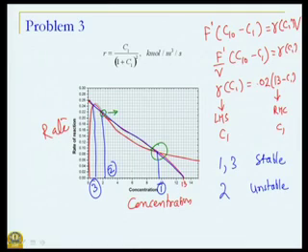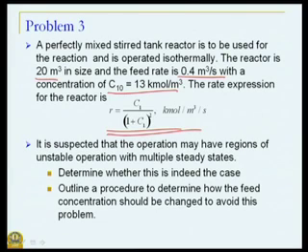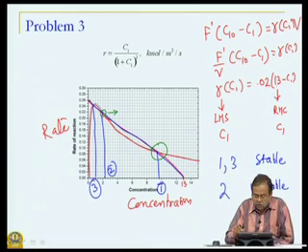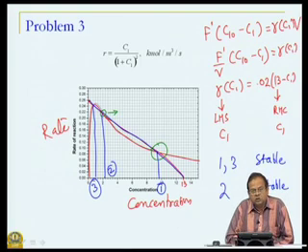So, now how do we determine how to avoid this? That means, the intersection of these 2 curves, right hand side and left hand side, must be a single point. What does it depend on? It depends upon the slope 0.02, but what is our question? We want to find out under what conditions feed concentrations it should remain unchanged. So, we keep feed rates same, but we change this feed concentration from 13 to a different value.